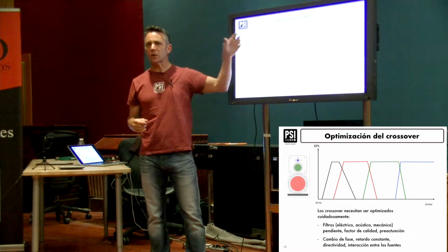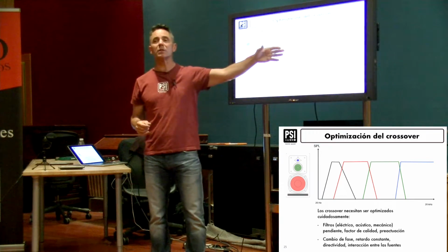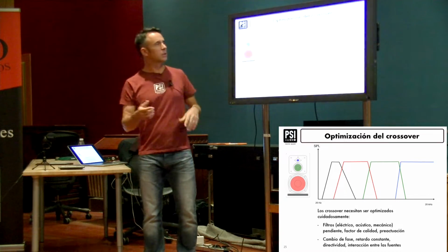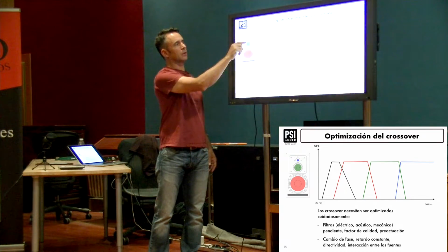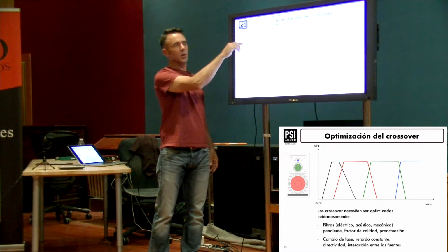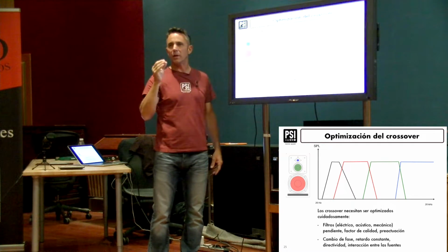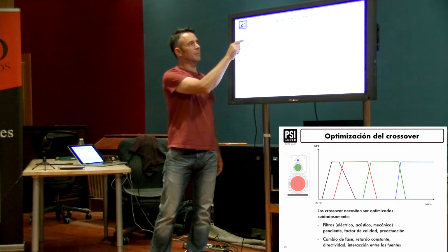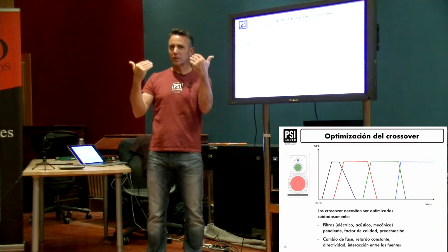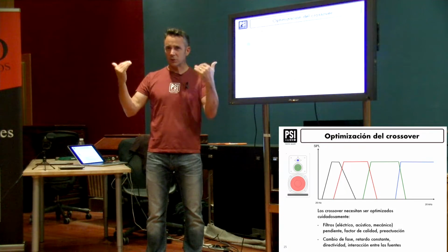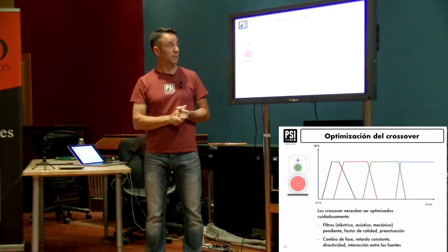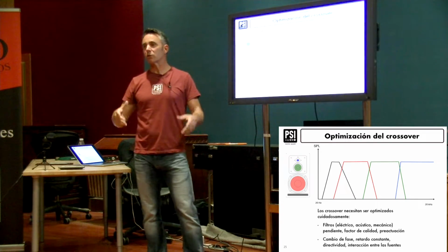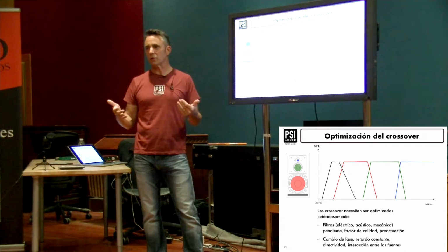That's one of the key elements, and directivity is also important in these crossovers. Ideally you want all the frequencies above coming out of here and all the frequencies below coming out over here, so that at no single time do you have the same frequency coming out of both, which would create some interaction that can be positive or negative in some places. But that would mean having an extremely steep crossover, which creates enormous phase rotation and all the rest.